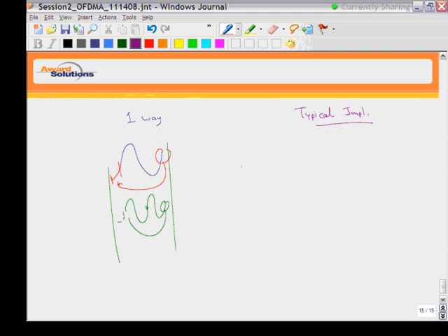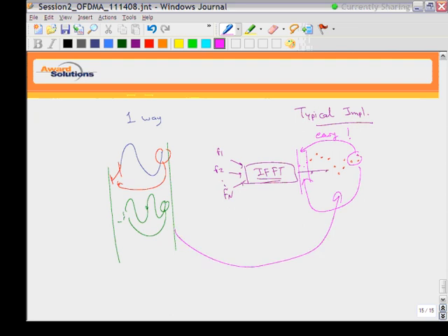In a typical implementation, we will see a little later today that there is some processing, IFFT. So we give all the subcarriers to this IFFT and it will combine the signals. So we already have all these signals that we will transmit. Then we just take the last few samples and add those samples at the front. So very, very easy, just a single step operation. Just take the last few samples, append those samples at the front, and you are all set. These two are equivalent.